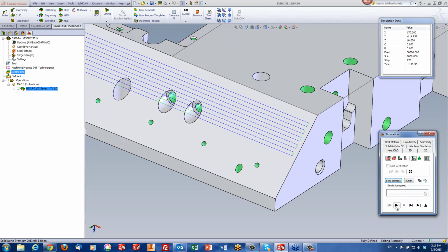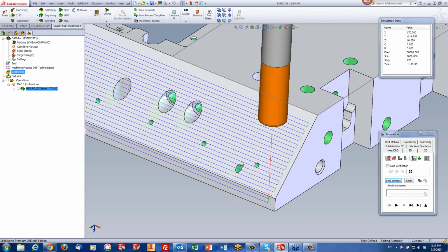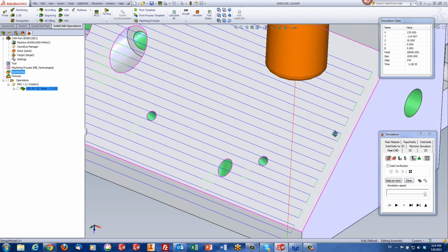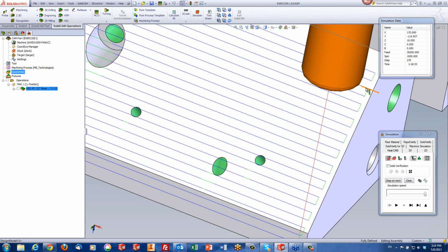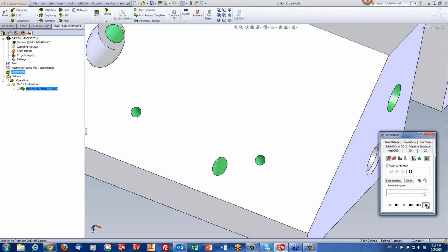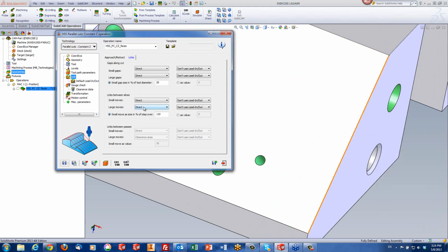If we take a look at the actual toolpath, you'll note that when it finishes at the edge, it goes directly down and then goes over. I'd rather have it, when it gets over here, blend itself around and come back in instead of going into a sharp turn over here. So we can use a different option. We have here an option called blend spline.